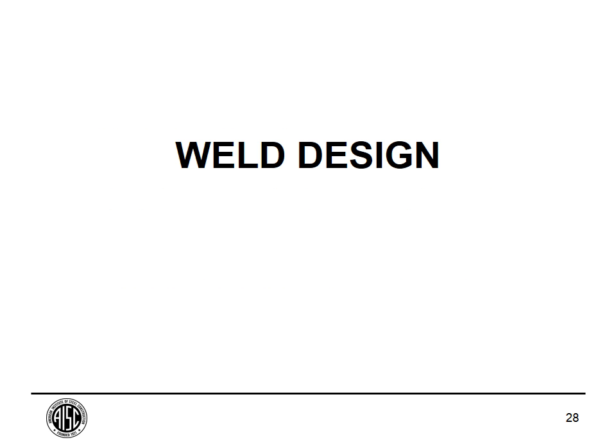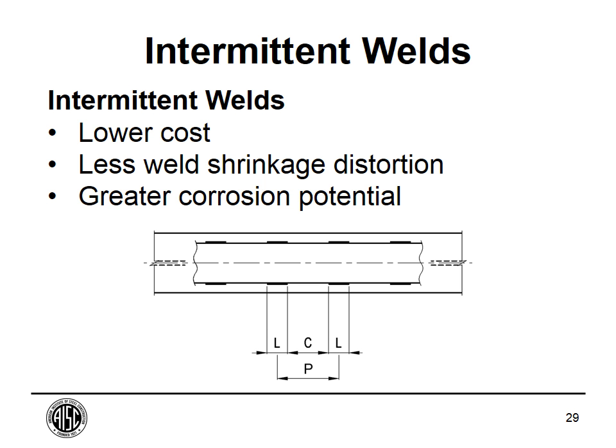Okay, our next unrelated topic, we're going to move on to weld design. Now I've got 2 good topics in weld design. The first one is going to talk about stitch welds. One thing about stitch welds, you're obviously going to get a lower cost because you have less welding. You have a little bit of cost in the measurement of these, but the cost of the welding saved is going to far outweigh the cost of the measurement.